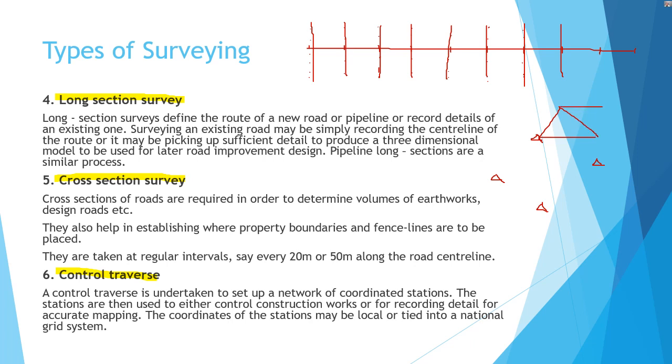If you build a structure over here, then you need to have some reference points here. So to build a network of these reference points is a control survey, or to determine a number of control points here for the other surveying work.